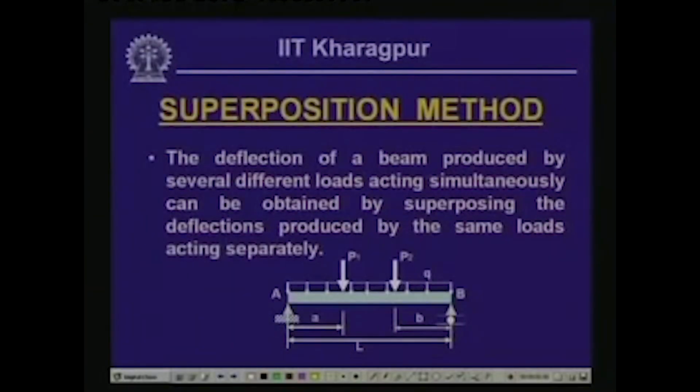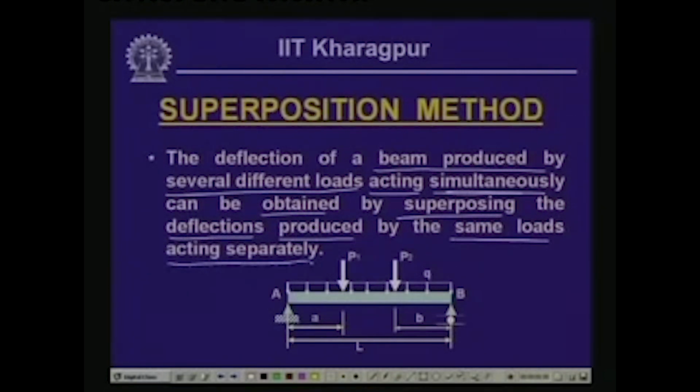In fact, that is what we call the superposition technique or superposition method. The superposition method says that the deflection of a beam produced by several different loads acting simultaneously can be obtained by superposing the deflections produced by the same loads acting separately.